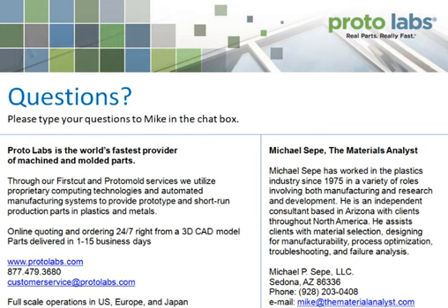So, just imagine a situation where you have a, let's say, a flame retardant glass-filled PBT, and someone puts a concentrate in that that utilizes polyethylene. Now, polyethylene, as most people know, is not flame retardant. To make polyethylene flame retardant requires a significant amount of modification of the material. So, polyethylene, to be polite, is basically like high molecular weight gasoline.